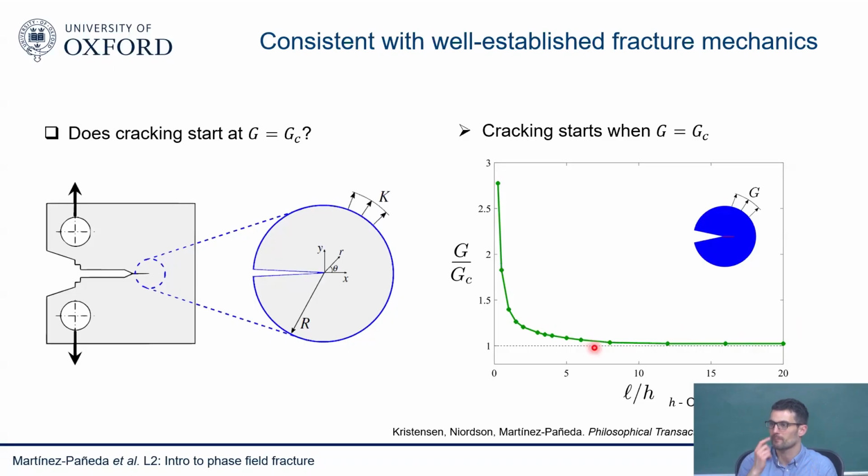This curve, is it sensitive to the type of material? Or will it change if I use steel or glass? No, it's roughly the same. It's normalized, so it only relies on Young's modulus, but it won't change much. So what you find in this curve you can apply everywhere. A rule of thumb that people normally take is 5 times: if you use an element size that is 5 times smaller than the length scale, you are safe.